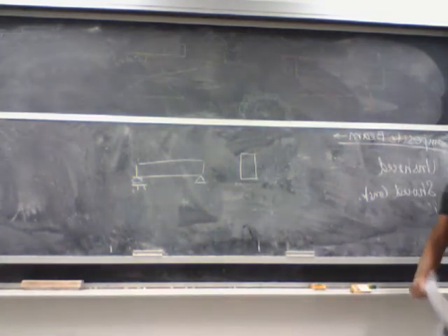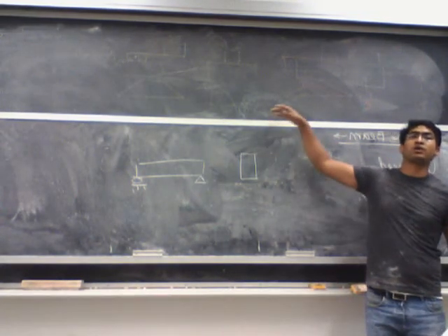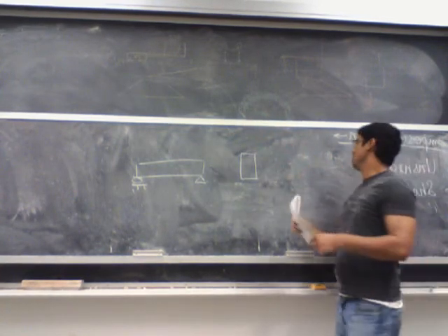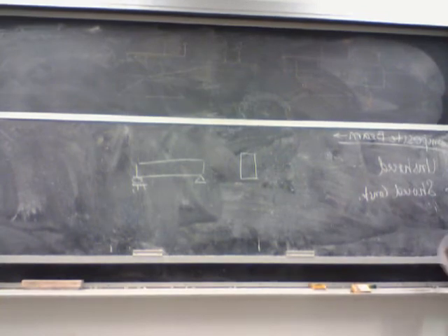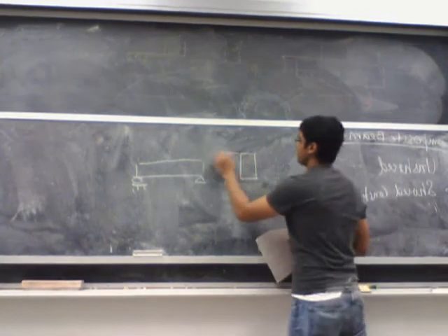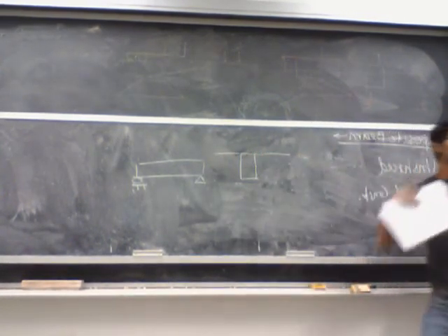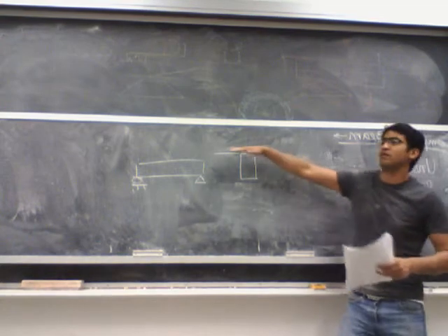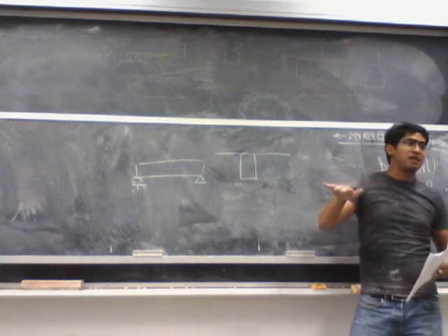And what you need to do now is put a slab on top of this, which is the next part of the composite section. In case of an unshored construction, you prepare the formwork, because you cannot just drop the liquid on top of the beam and expect it to make a nice thin slab. You need to provide some kind of formwork to make that slab.